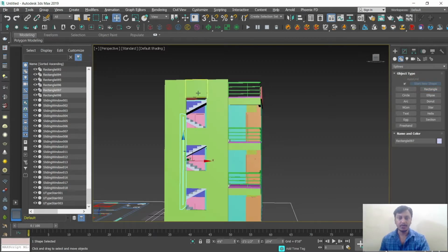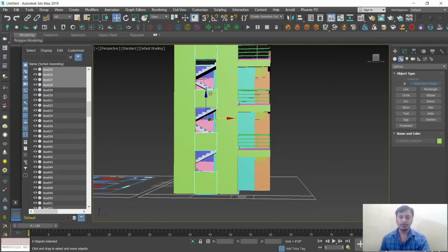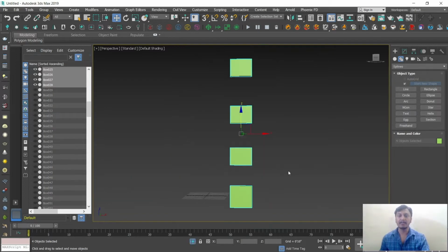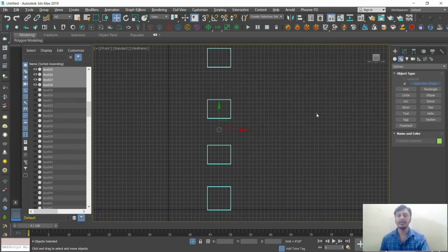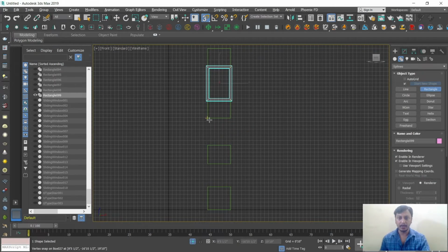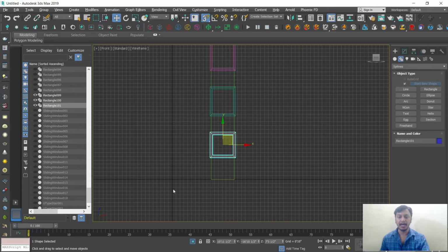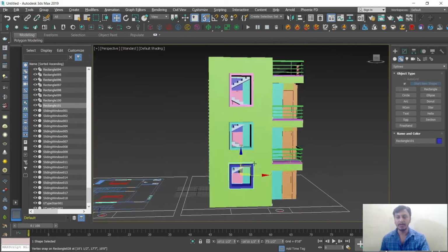Yes. So select a wall. So 4 things I have selected. Use Alt for multiple selection. In the bottom you can observe something called isolate selection. Click on that. The selected object will display, and everything except that will be hidden. So I am drawing a rectangle. 1, that is framing. 2, 3. Once your work is done, press back again, and you will get your normal view.